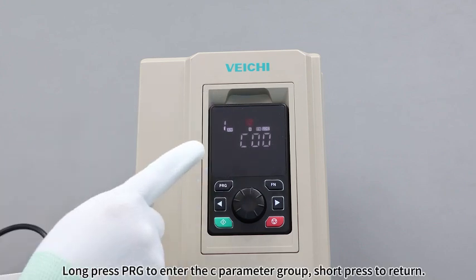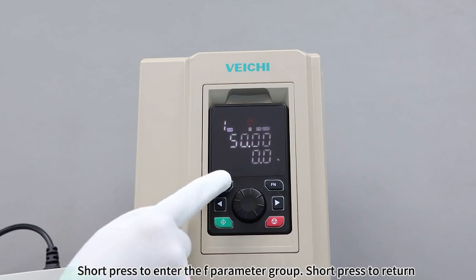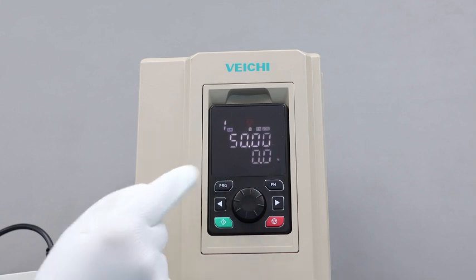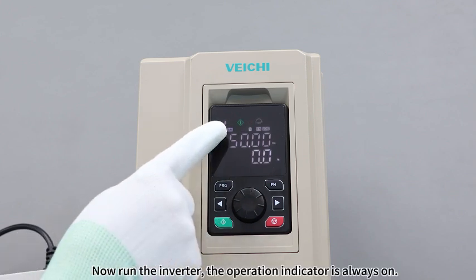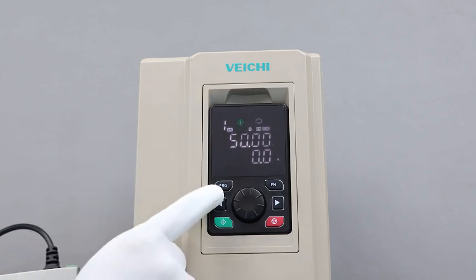Long press PRG to enter the C parameter group, short press to return. Short press to enter the F parameter group. Short press to return. Now run the inverter. The operation indicator is always on. FWD indicator light is always on.